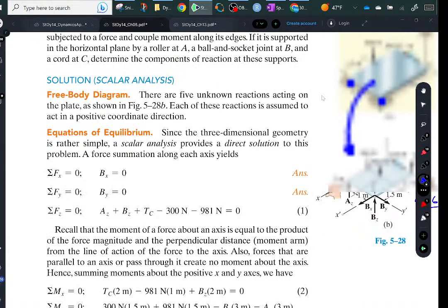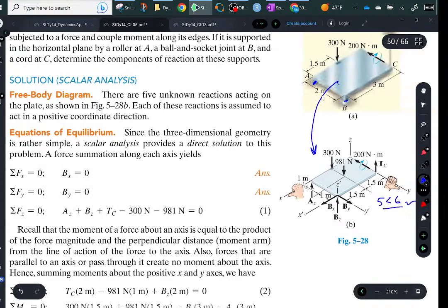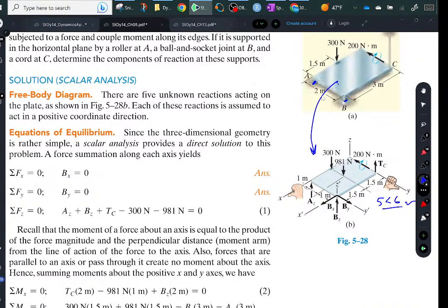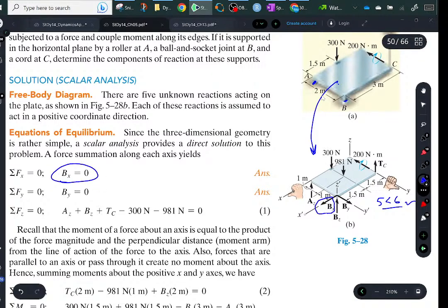So you look at this thing, first thing he does is he sums the forces in the X. Okay. Sum the force in the X. You get this one all by itself, and it's equal to 0. That simplifies it. But if I had an AX out here, then I would have a relationship between AX and BX. But I don't. And then the Y tells you that.